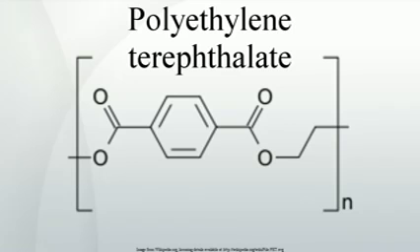Depending on its processing and thermal history, polyethylene terephthalate may exist both as an amorphous, transparent polymer and as a semi-crystalline polymer. The semi-crystalline material might appear transparent, particle size less than 500 nanometers, or opaque and white, particle size up to a few microns, depending on its crystal structure and particle size.